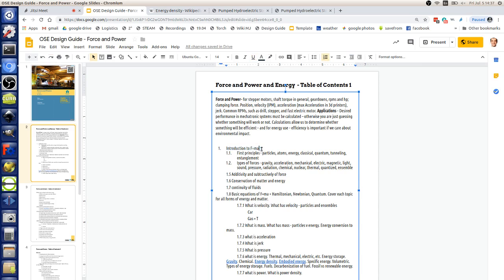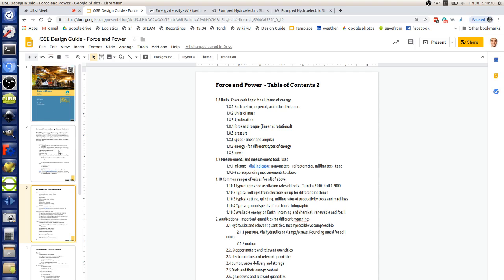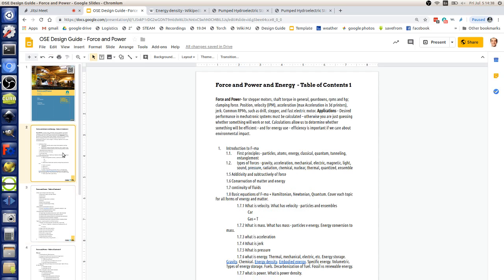Hydrogen sounds scary, but you can look at some videos of what happens with tanks bursting. When you have 100% hydrogen and you burst that tank, it won't explode. It will make a high velocity flame and just leak out and flame out. It doesn't explode unless you have over 4% oxygen, in which case it's explosive. As long as you're storing it pure, which you can control, then you can do it. I'm definitely a fan of it. Hydrogen does not explode by itself; it has to be mixed with oxygen. Typically when you have a tank of hydrogen and it just goes out, it's not particularly explosive. It's only when you've got oxygen within it already.